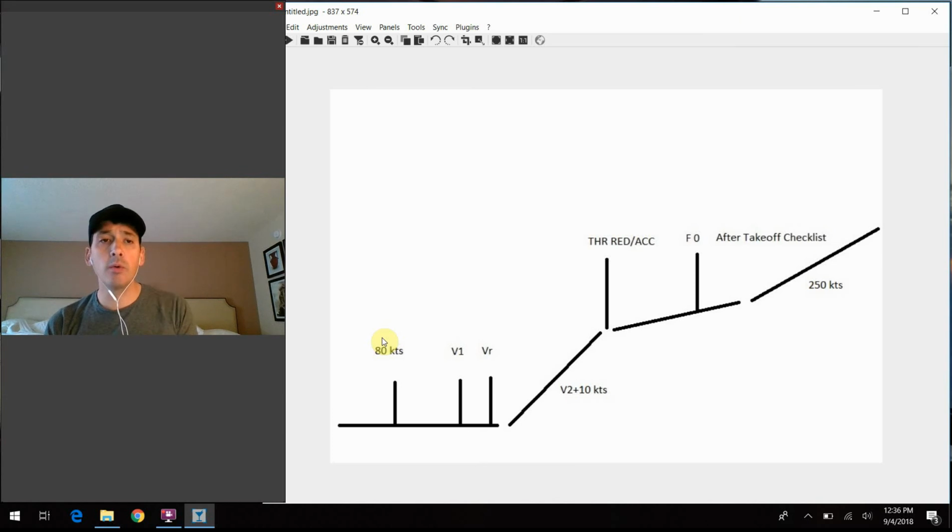and theoretically allows, from a performance standpoint, that you are physically starting the reject of the takeoff literally before V1, because if you're after it, technically you're supposed to be going, and you don't necessarily always have the performance, once again, to stop the airplane safely, and it's better to take it airborne and deal with the issue there. So that's kind of why we do that, kind of an interesting thing.